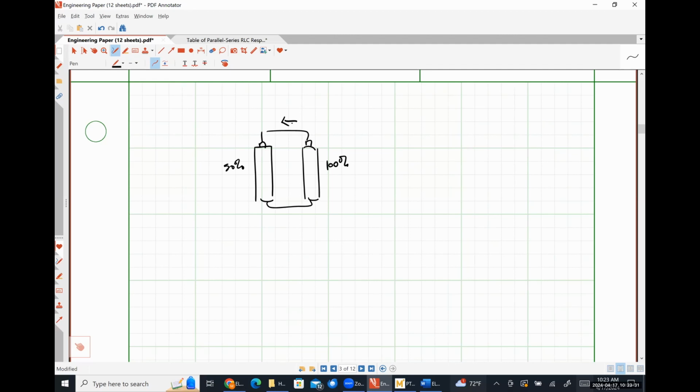That is incredibly similar to these really interesting but completely useless electromechanical motors that people started making when MEMS got big. It's effectively a capacitively actuated motor, where you use parallel plate capacitance, turning capacitors on and off to drag a gear around its cylindrical path. So it's completely the opposite: it's electric field driven instead of magnetic field driven. They tried to use it for micro scale drills, I think in dentistry, but I don't know if anything ever came out of it.